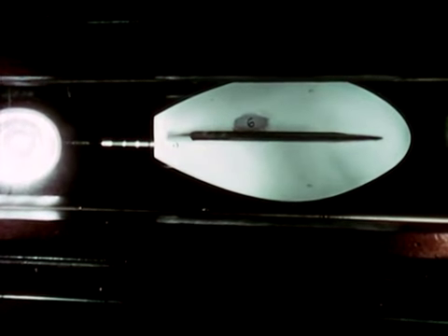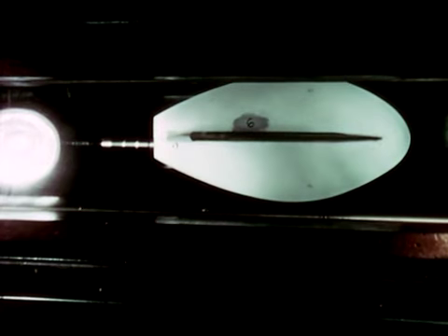As the tests proceeded, a model fluttered over a very narrow range, giving a lower limit to the flutter boundary. Weaker models showed the increasing flutter range. The slow-motion camera provides the indication of the flutter mode and indicates the rugged qualities of the models to withstand these forces.